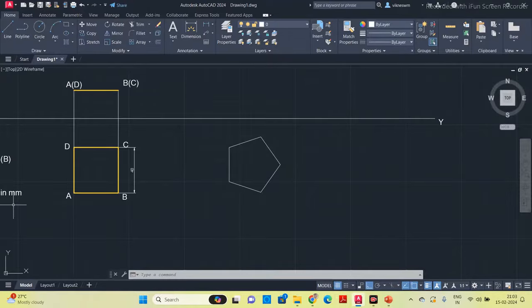And the next thing is we have to name the corners. So starting A, B, and after placing it, you change it to E. So once you have the top view, meaning once you have the true shape, take a line and project from each corner until the reference line.